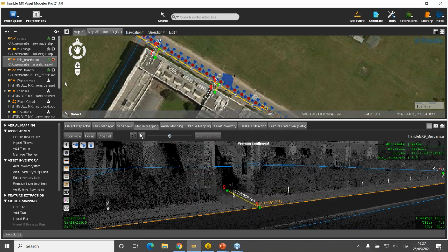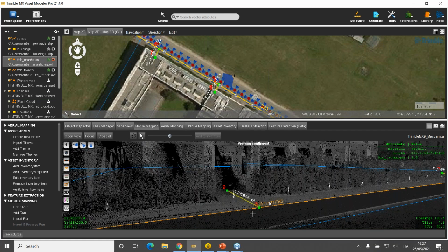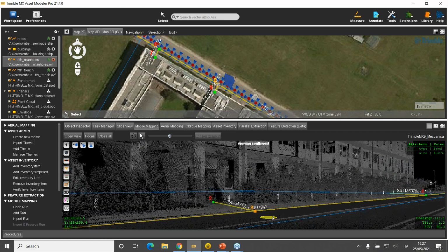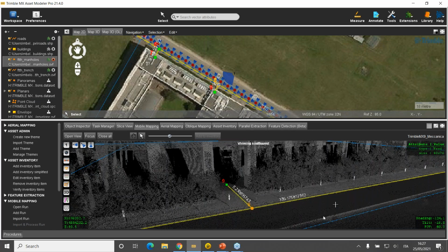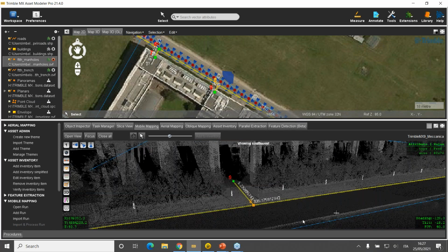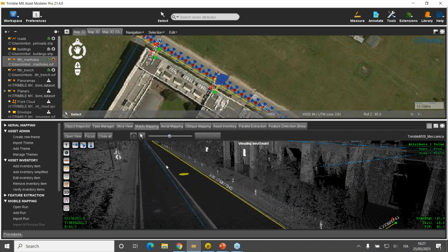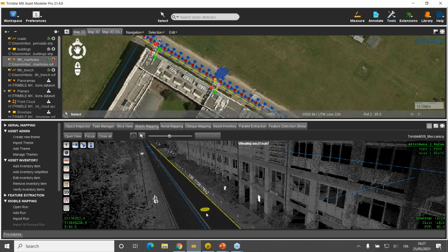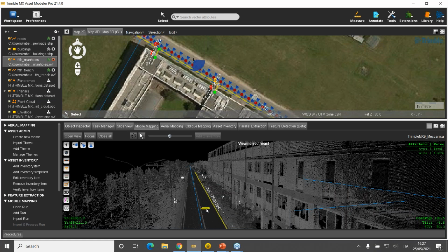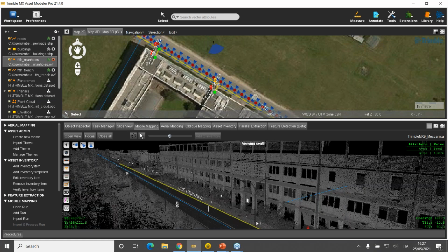So this is the case of the line, but very similar to this, we could also make inquiries to the manhole features which are available, and in this case we can have a look at the type of manhole. Is this a feed? Is this a pool? Is it an intermediate pool for the fiber optic cable pulling activities? Which is the size of the manhole? So all attributes which can be created or again just imported and used, and all of these being part of basically the design for the future fiber optic network.